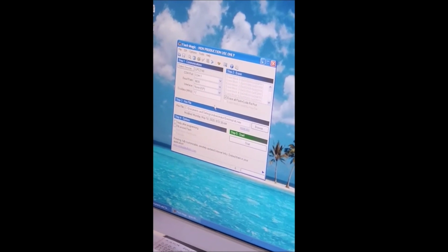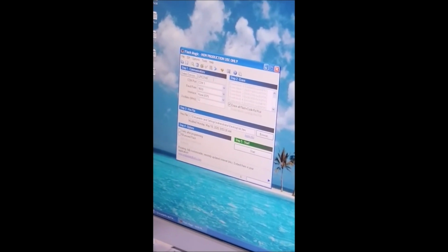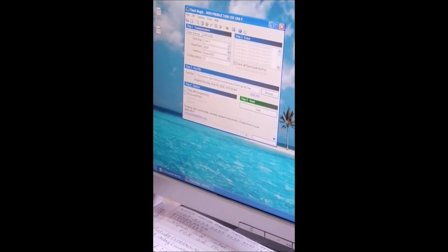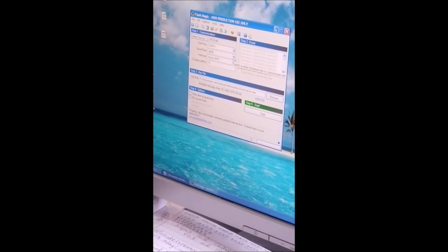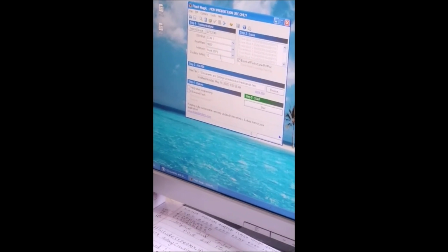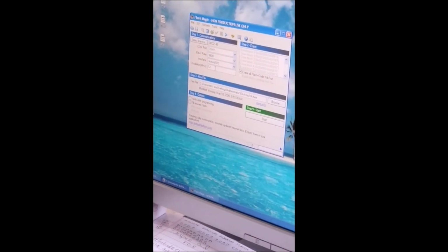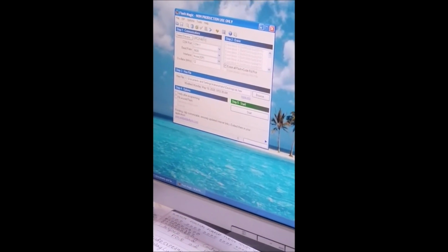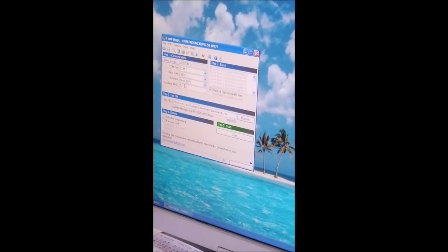So here you need to select the device, and the COM port is COM1. The COM port is nothing but the cable which we have connected from the CPU to the microcontroller. That is COM1. Then the baud rate, for all the programs for this COM1, the baud rate should always be 9600, the interface is non-ISP, and the oscillator is 12 megahertz. So this is the same for all the programs.